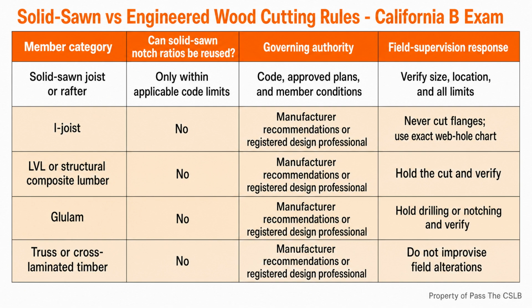For engineered floor and roof members, I do not authorize a cut, notch, or bored hole from memory. I verify the manufacturer's published detail, or I obtain a design from a registered design professional. That rule sounds strict because it is strict.